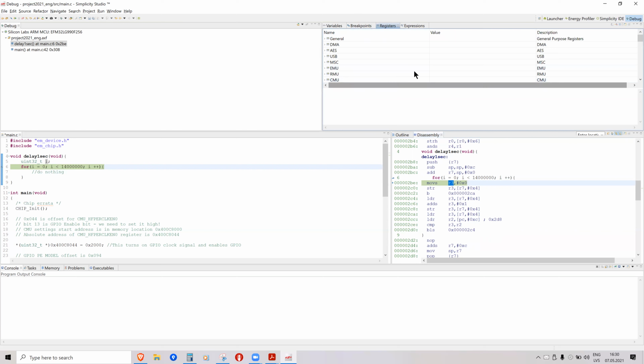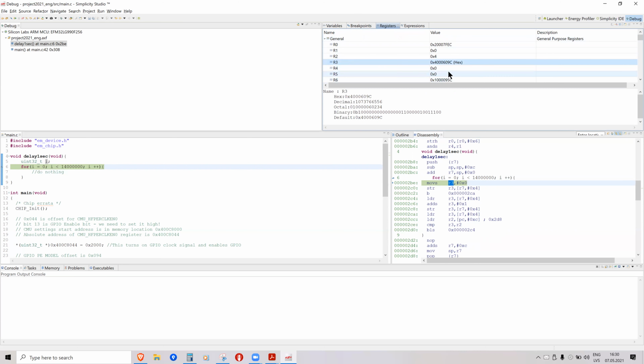So I can click on registers view, in general and register R3. I hope that it will be equal to 0. So to walk through instructions in assembly, instead of clicking step into, you click instruction stepping mode first, it's active, and then I click step into. And as you can see, this move means move 0 to register R3. And this S just tells if it's integer, word, or something like that.